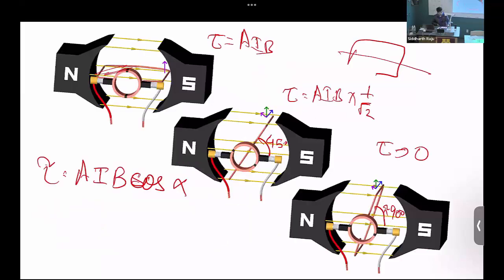Yeah. So there's going to be a period where at this angle, exactly here, this brush is going to short both the top copper and the bottom copper. That's going to mean whatever EMF is developed across this loop is going to get shorted. We are shorting the rotor winding. How can we get around it?